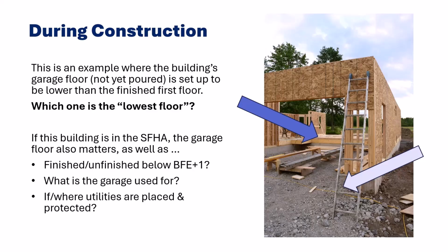If either is going to be below that BFE plus 1, they'll need to meet those enclosure rules: unfinished or flood-resistant materials space, proper flood openings, and limitations on use, storage, parking, access. Have a construction inspection checklist that helps you keep an eye out for these items.